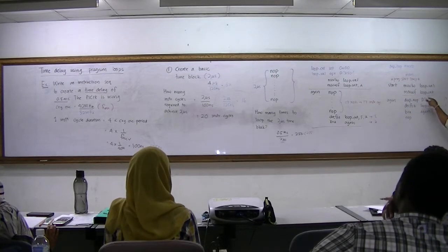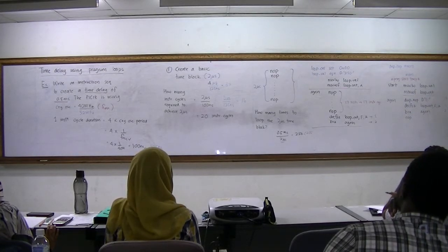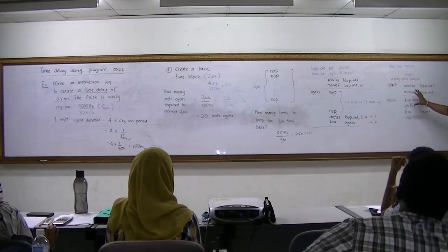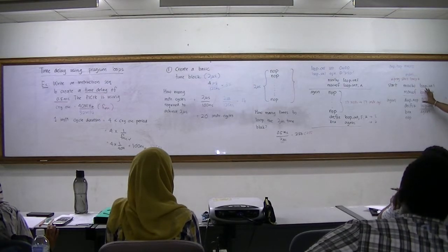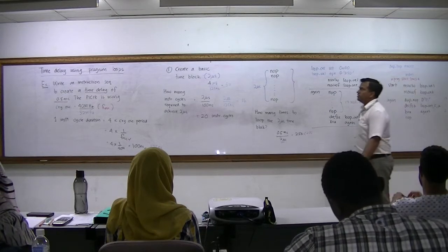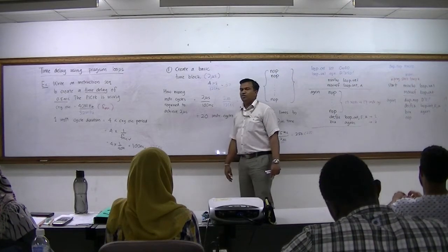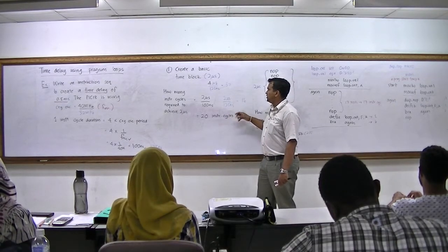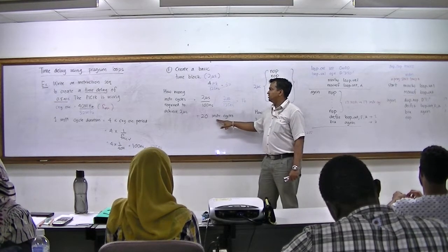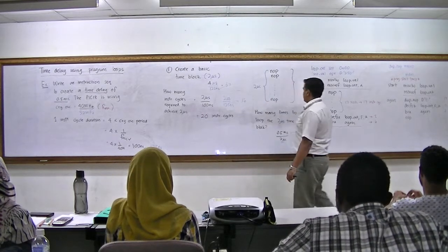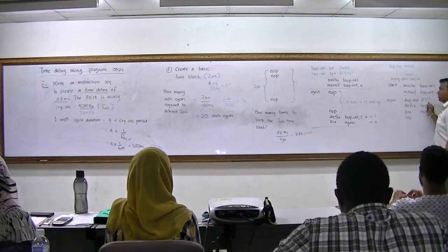And then you just change this value. More or less, you see this structure is the same. For the loop delay, this structure is the same. The only thing that will change is this value. And another thing we saw is, if you change the basic time block, if you don't want to use 2 microsecond delay, you want to use any other value, also can. The only thing that will change is how many instruction cycles you need. That's all. And you need to change here accordingly.